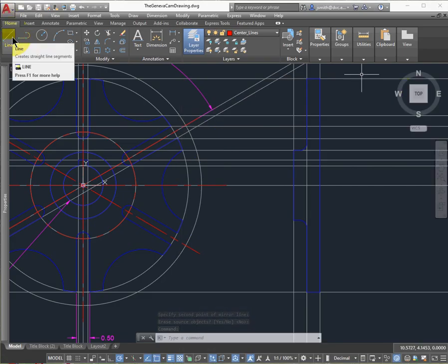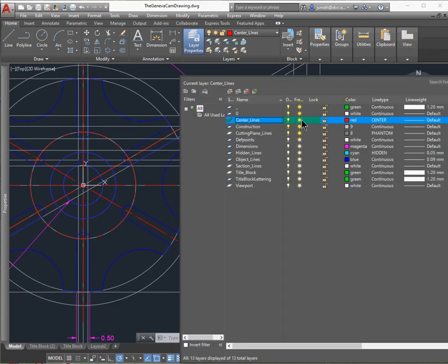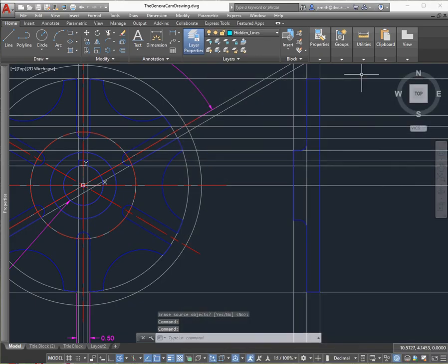I'm going to make some hidden lines here. All right, so I'm in hidden line. Now, because I already have these construction lines, but there's still a lot going on here, so I'm going to be really careful what I'm doing here. All right, so that's a hidden line, and there's one below it. This is where the key is for that cylinder. And then below it, I only need to make one, because the other one was the key.